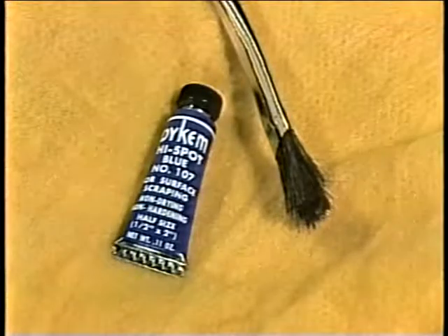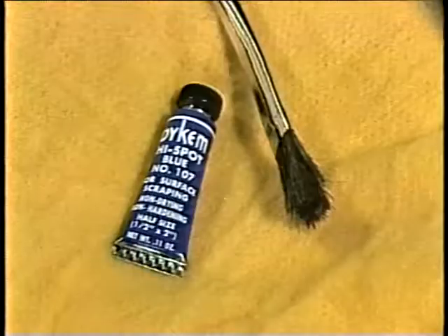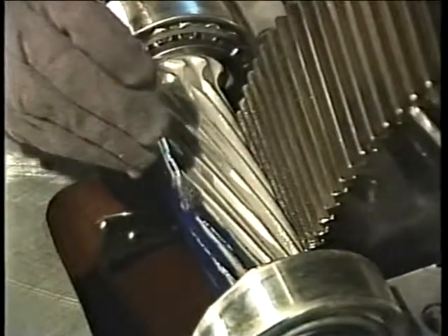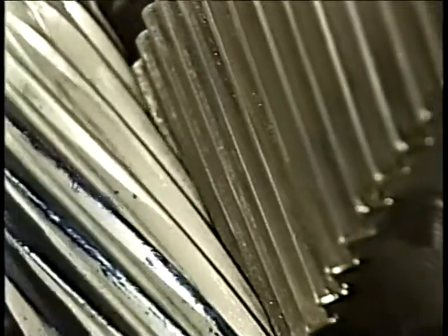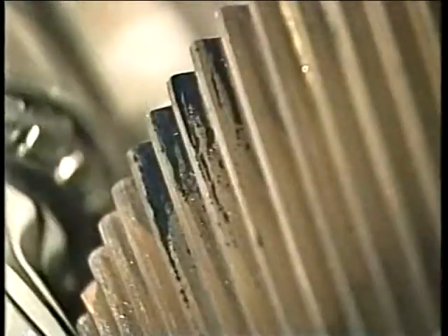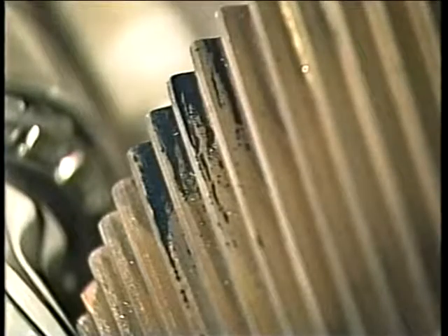One of the ways in which tooth contact can be checked is through the use of a bluing compound. Basically, bluing is applied to one of the gears in a mesh. The gears are then rolled and the bluing transfers to the other gear. This leaves an impression of the contact pattern on the second gear. This pattern can then be checked to see that the gears are properly aligned. In this case, the bluing only transferred to one end of the mating gear. This indicates that a severe alignment problem exists in this gear set. Gear manufacturers normally provide information on proper gear tooth contact, so be sure to check your equipment's technical manual if you suspect a misalignment problem.